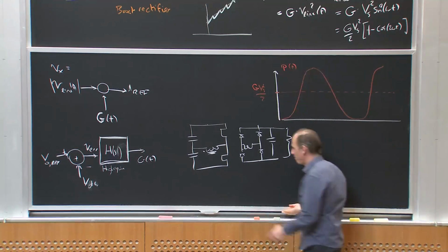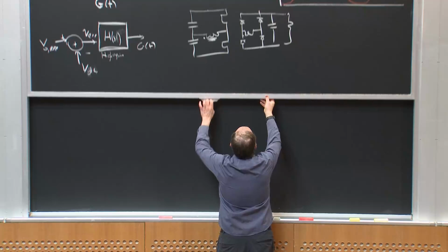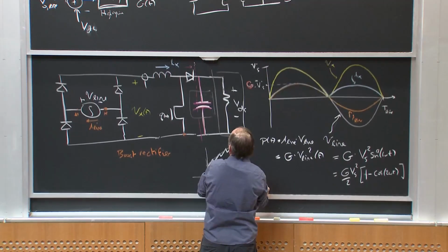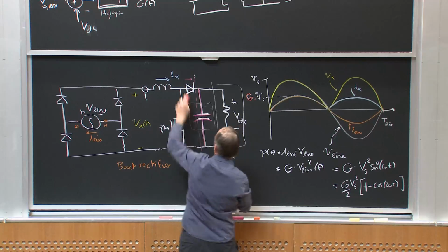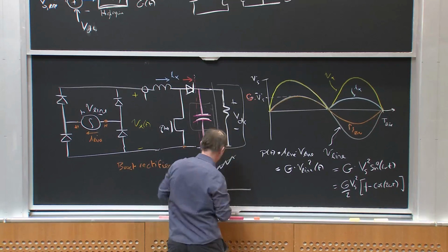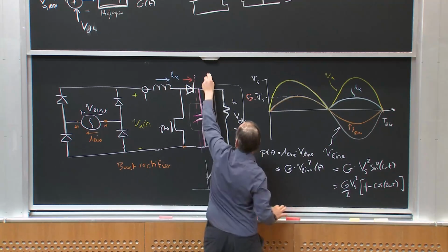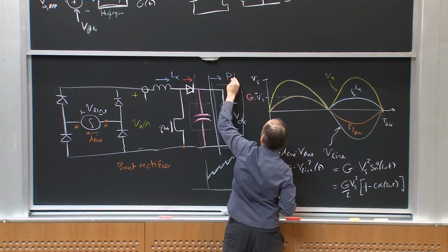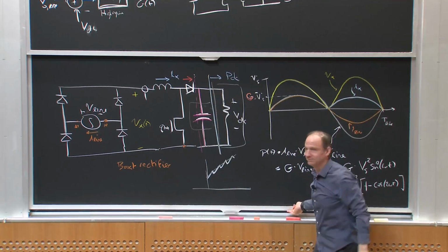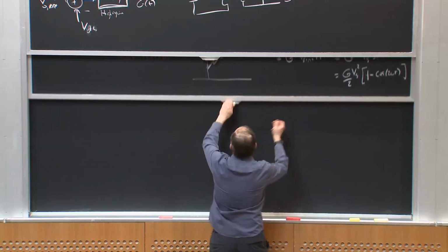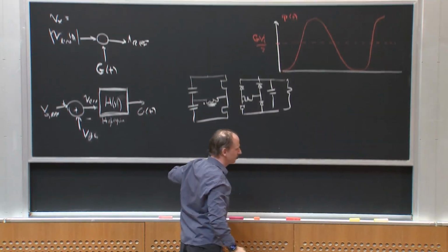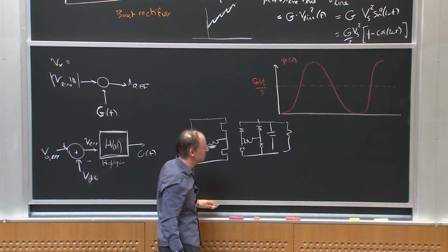Now, if I imagine the orange is what's being sourced, right? So that's sort of what power is coming to here. If I imagine what I want going to my load is DC power, right? What does that look like? Well, if I have a DC voltage and a DC current drawn by my next converter stage, it's not really a resistor.